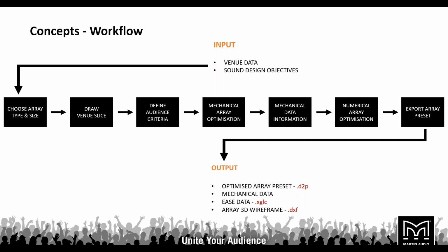We can export our mechanical data in the form of an HTML file, readable on any smartphone if needed. EASE data in the form of an XGLC file, which can then be combined onto a GLL within EASE. Quick note, this is for full EASE, cannot be used with EASE Focus, but we can use that for 3D